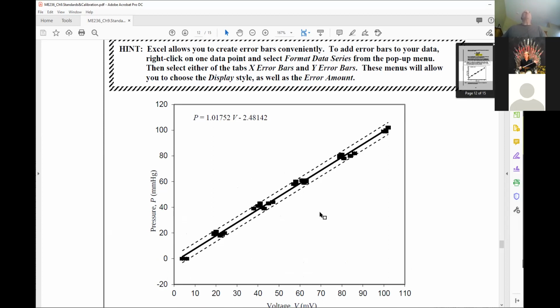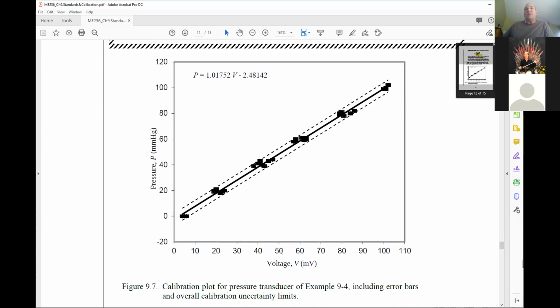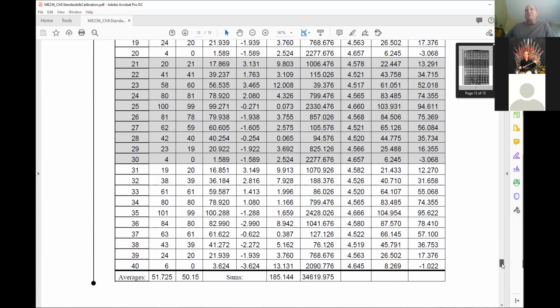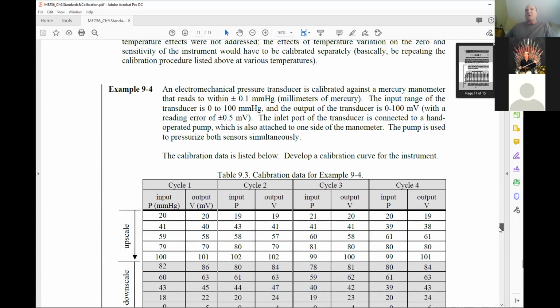No, what you'll do is for those you'll use the voltages, and you can get the uncertainties through the curve. So what I would do is there's a couple ways to do it. For example, if this was my graph that I'm showing here and it was exactly at 50 millivolts, I would just follow that up to where it intersects your lower confidence limit. And then what does that read as mass? And then your nominal, and then your upper. And that'll allow you to get a rough estimate of it. Does that make sense? So your curve should tell you, and it should be a pretty tight value, as you'll see. It's not going to be a large spread, but you do want to get that. Does that make sense to everybody? Yeah, that makes sense. Okay, good.